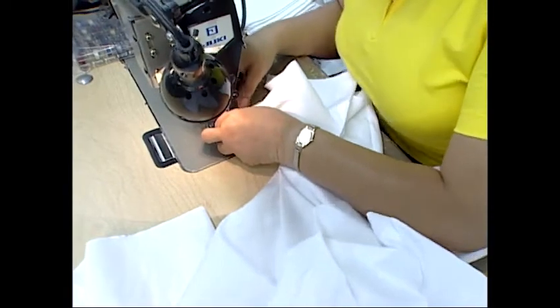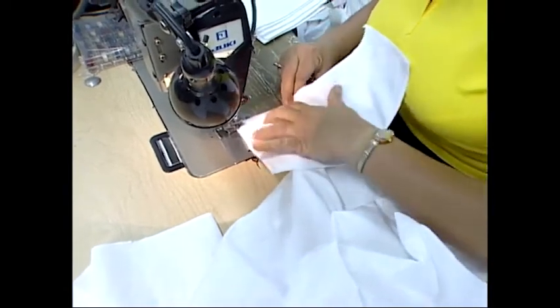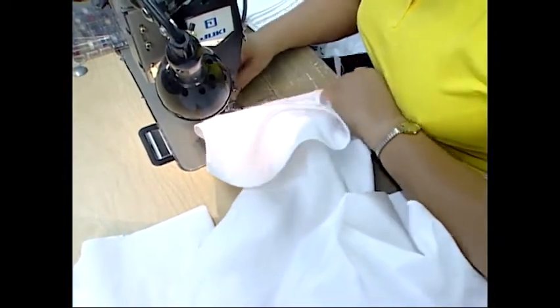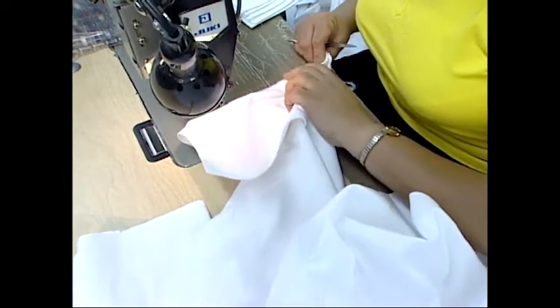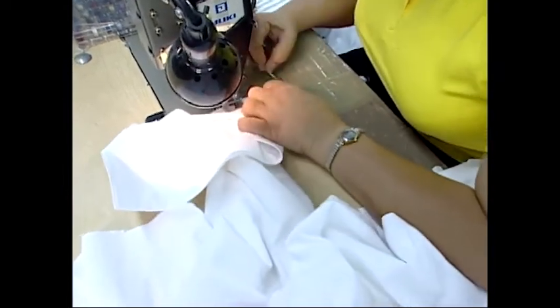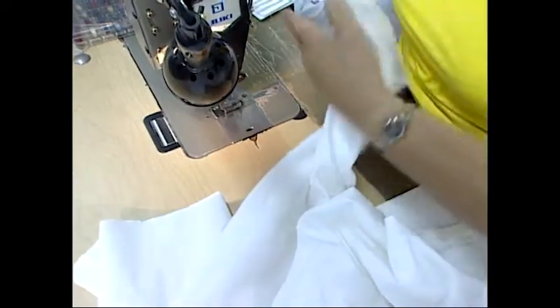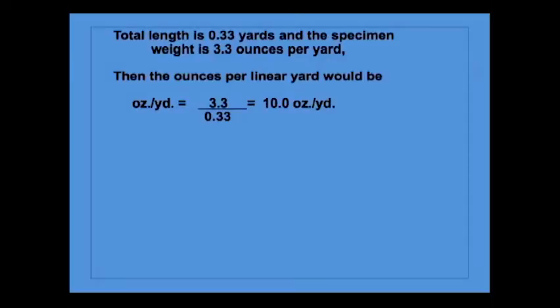Textile and apparel manufacturers often communicate fabric weight in terms of weight per unit length and length per unit weight. Ounces per linear yard and grams per meter are common expressions of weight per linear length. These expressions have importance, especially for cut and sew operations. In the above example, where the piece of fabric is 1.67 by 0.33 yards, the entire width of the sample